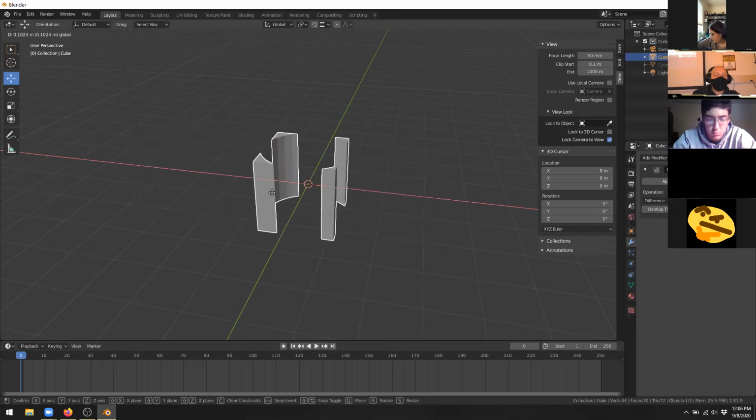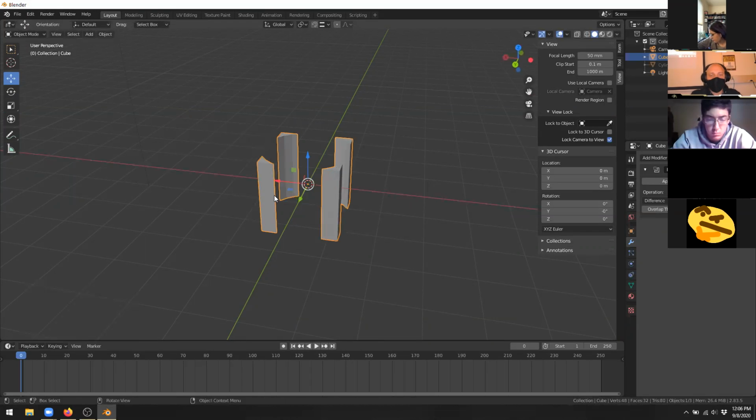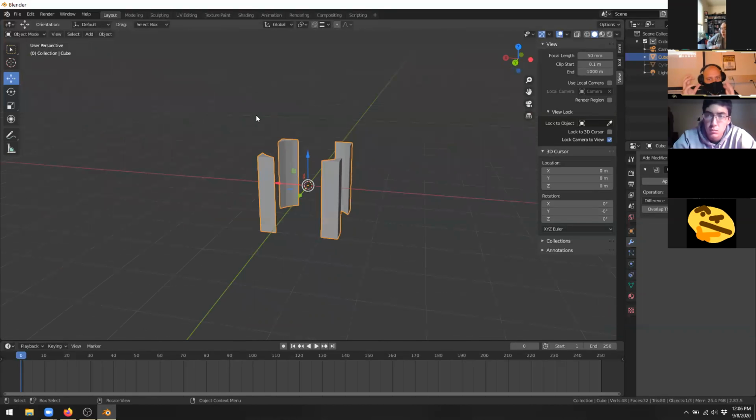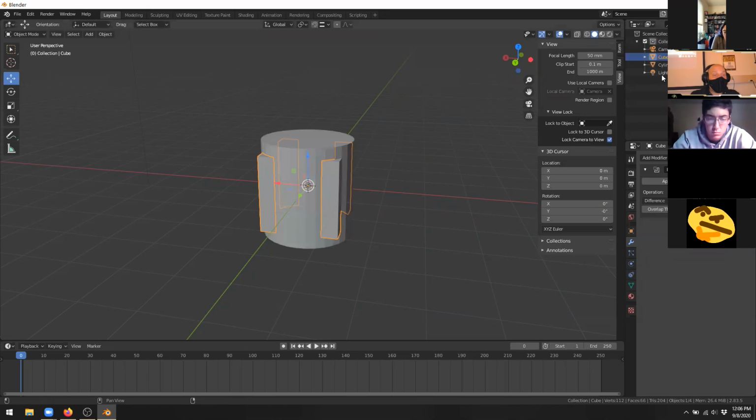But I imagined that this shape I have right now would move, so those four little pieces are going somewhere together. The thing we have to remember is that both elements, the cylinder and the cube, would need to go together if we left it this way. Easiest way to handle that would be to temporarily unhide the cylinder.